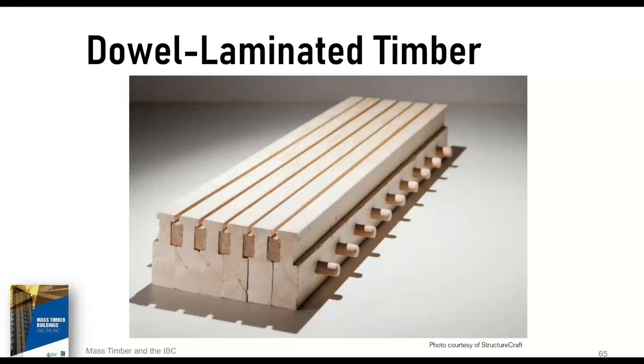Panels are made from softwood lumber boards, 2x4s, 2x6s, 2x8s, etc., stacked like the boards of NLT and friction fit together with dowels rather than mechanically stitched with nails. Typically, the dowels are made from hardwood lumber. The dowels hold each board side by side, similar to how nails work in an NLT panel. And the friction fit lends some dimensional stability to the panel.